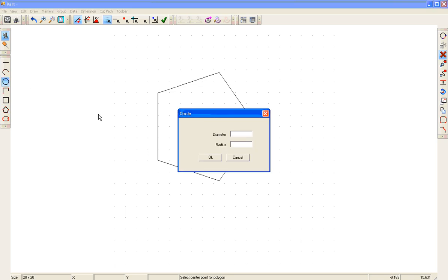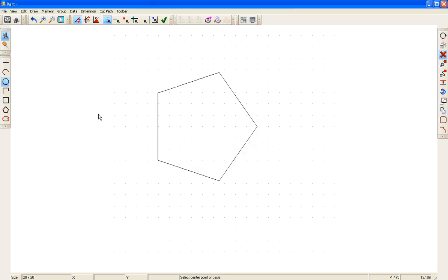I'm just going to place a little circle out here on our center point. Since I selected the corner tangent, that's telling me from this center point right here to each of my 5 corners, it's going to be 5 inches. Let's go back to draw.